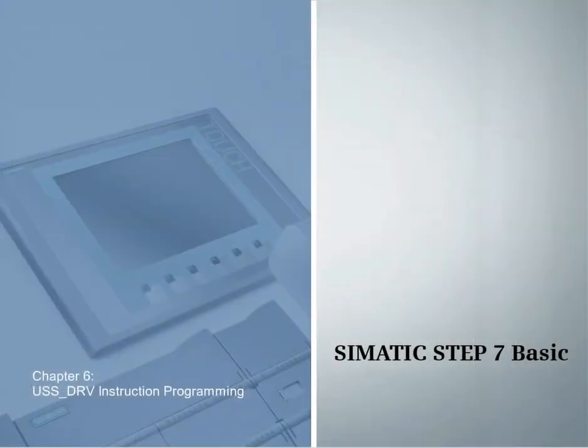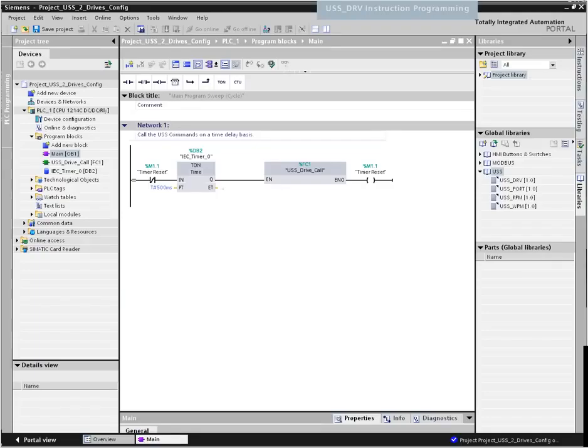Chapter 6. Call and configuration of the USS drive function block. Only call the USS drive FB in the main OB1. We use a TON timer on delay with a delay of 500 milliseconds to guarantee the consistent updating of drive states. In this example, the USS drive call function contains two USS drive calls. Below, we look at how to configure these drive calls.